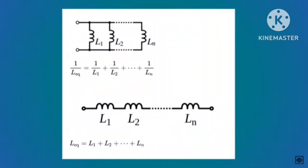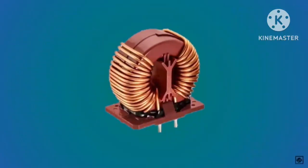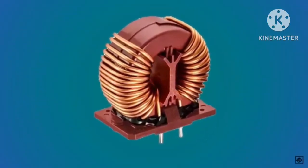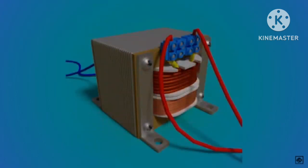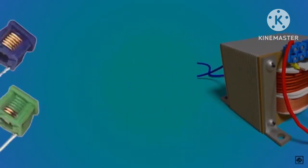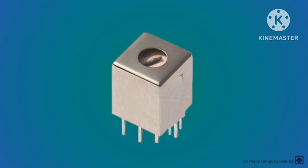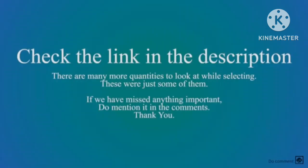You can combine inductors in series and parallel to obtain certain values. There are also coupled inductors. They are used to electrically isolate two circuits but allow power to be transferred. If the winding ratio is different from 1:1, then it can act as a transformer. At last, there are some variable inductors. In these inductors, the core is moved to change the inductance or one of the terminals is moved, similar to the rheostat. All tables, charts, and graphs are available in the link in the description.